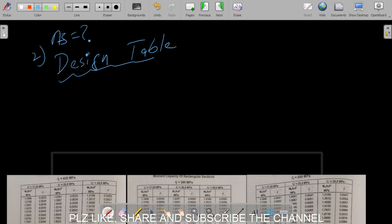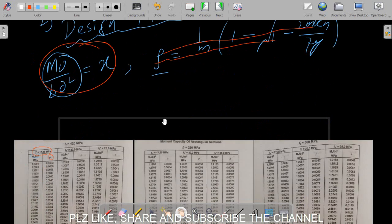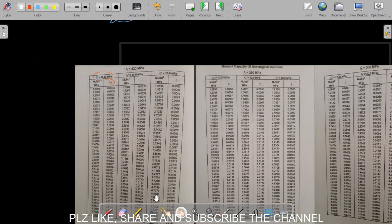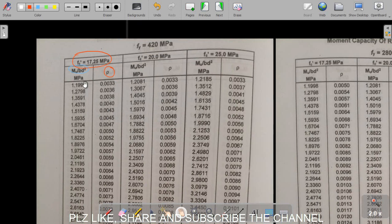When we are using design tables, what we need to find is the Mu divided by bd square value, right? Let's say this is x, and we need to choose this Mu by bd square value. We choose that value in these tables, and in these tables we will find our desired value.